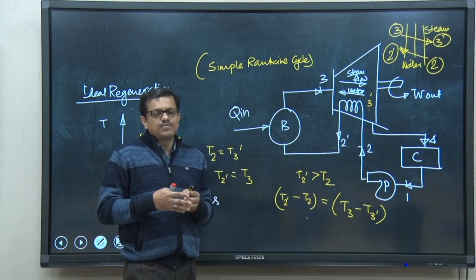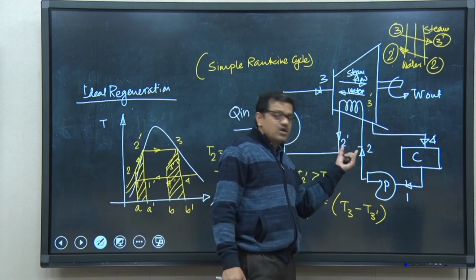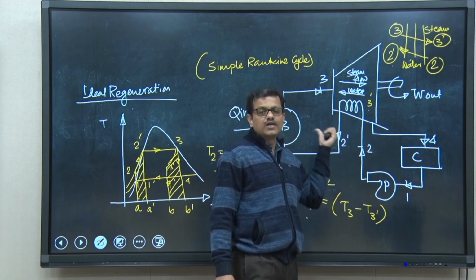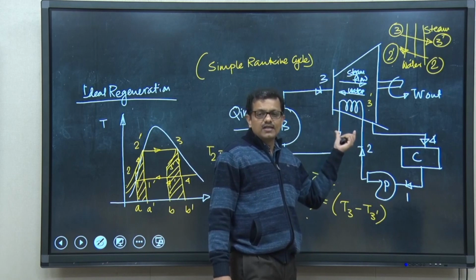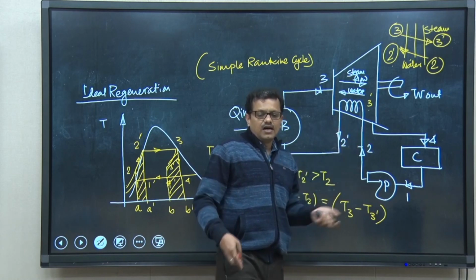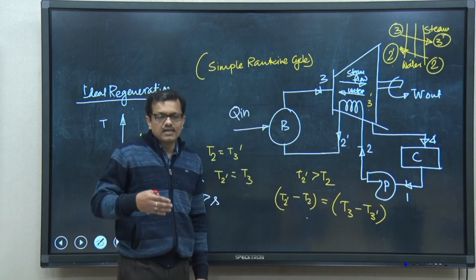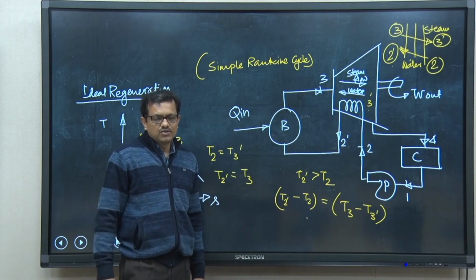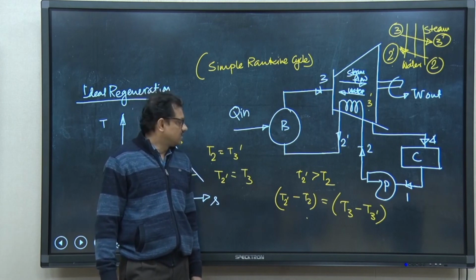It should not be a proper design if we do not think about the removal of air from the feed water before it enters the boiler, because the presence of air in the feed water can initiate corrosion of the boiler pipe. So, that is again very detrimental from the perspective of the boiler operation.